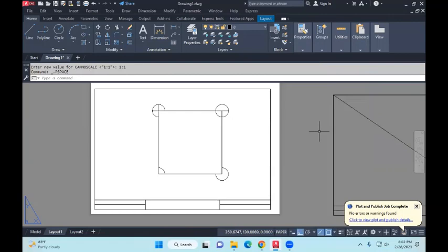Here is the tricky part, most of the students will face it. It's like a picture frame. You prepare the frame, and now you're putting the face in the center, which is your drawing. So the viewport gives you the drawing and the title block is your frame. So make sure you play those dragging points properly so that your picture is in the center, oriented properly.